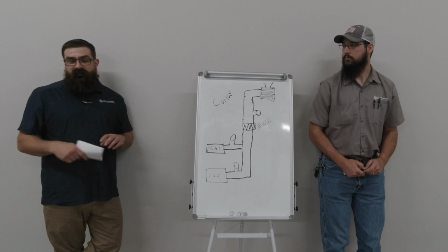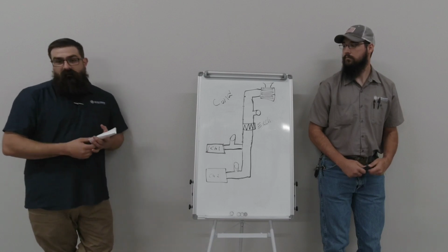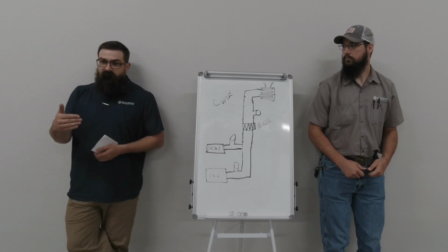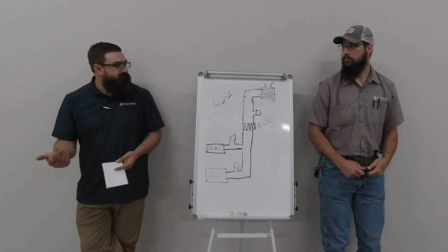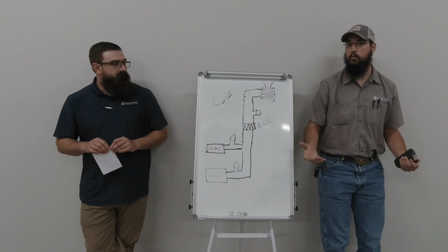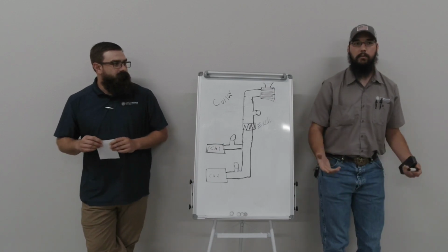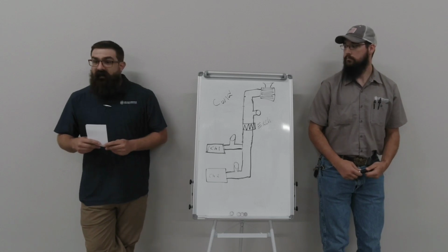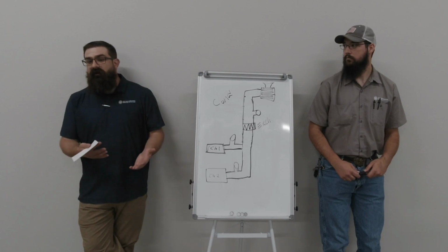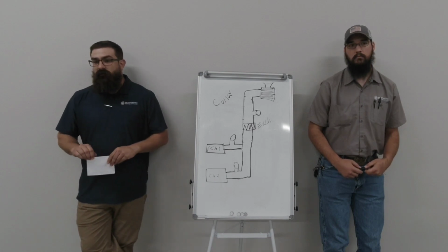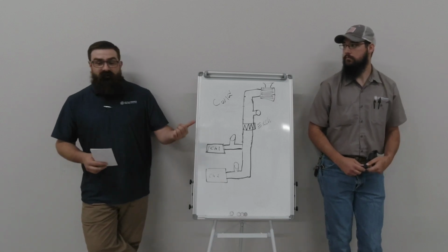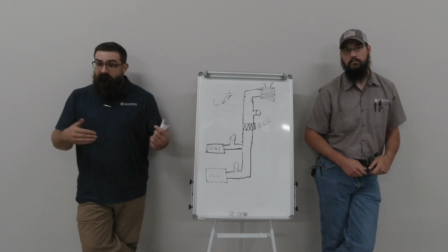Just like we check on those water source heat pumps, right? So if you have condenser water entering a water source heat pump and it's high, I don't know what your pressures typically run, what would you say? Say it's 60 pounds entering and on a normal day, 40 pounds, 30 pounds leaving. If it's running 10, well, you've got an extreme pressure loss, so something is plugging that condenser. So if it's down to 10 PSI, he's saying it runs normally 30, 40. So you have some pressure loss, right?